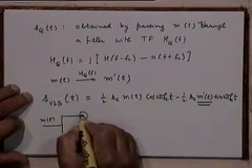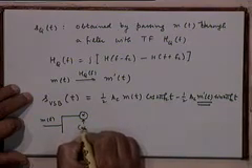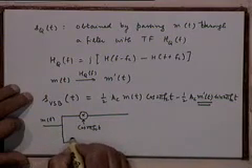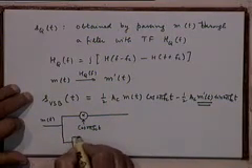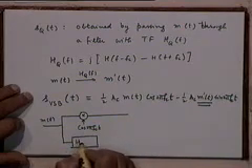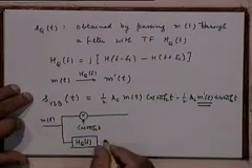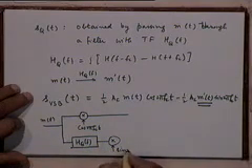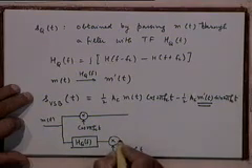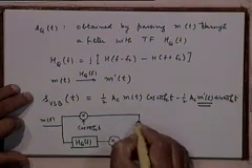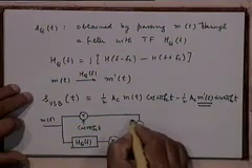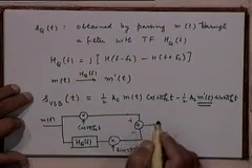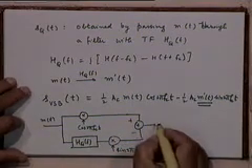The in phase part will be obtained by simply multiplying with cosine 2 pi FCT, and for the quadrature phase part, before we multiply with sine 2 pi FCT, you will pass it through this filter HQF, and then multiply this with sine 2 pi FCT, the quadrature carrier, and simply add the two or subtract the two, depending on which sideband you want to transmit fully and which one partially.